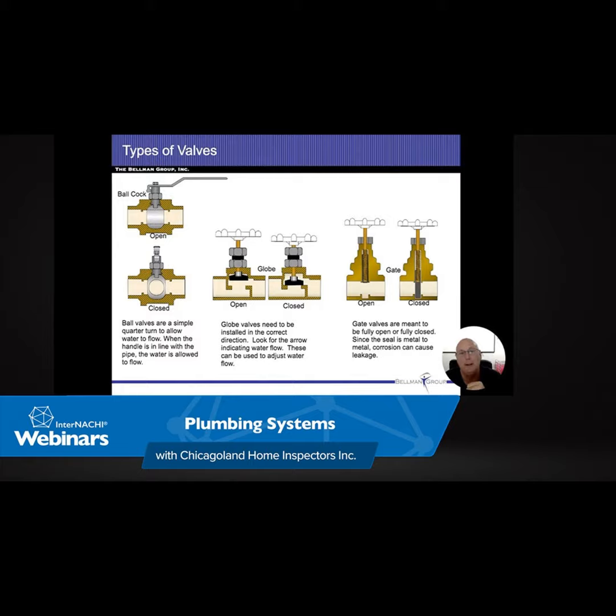So when you're looking underneath the sink, we really should be seeing a couple different pipes there. They may have one visible and one not visible. But if one does go up, do your best to get your phone or your camera back in there and take a picture of the underside, just to make sure we don't have an air admittance valve stuck in there trying to shortcut.